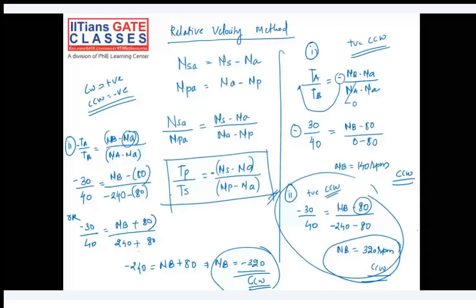Then depending on the motion of the gear, we understood the line of action, that is pressure line, angle of pressure, basically phi, path of contact, arc of contact, path of approach, path of recess, arc of approach, arc of recess. We have studied the formulation for it as well. We also studied the contact ratio and number of gears in contact, velocity of sliding, law of gearing, interference and undercutting phenomenon, and how we can avoid the interference in case of involute gear by providing the minimum number of teeth. Okay, and then we introduced the term of gear trains.